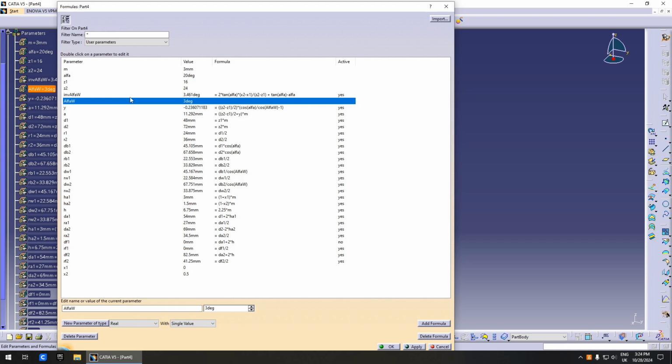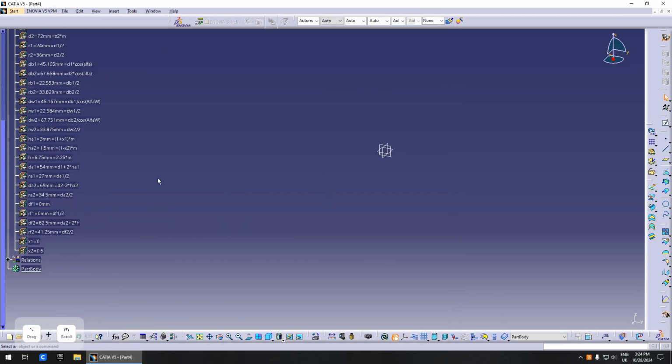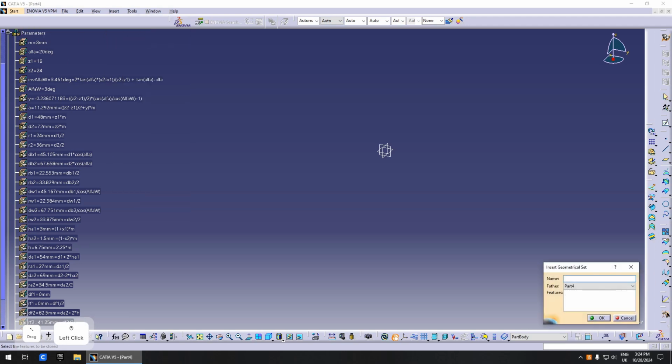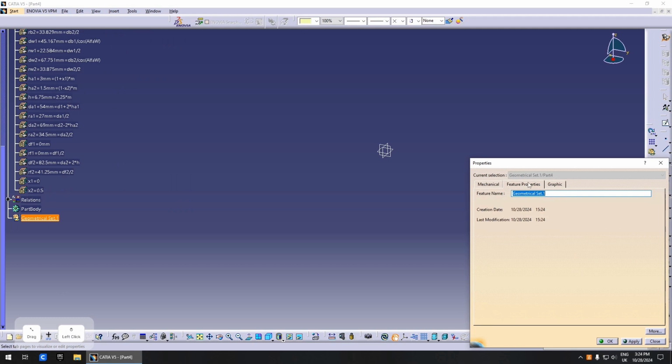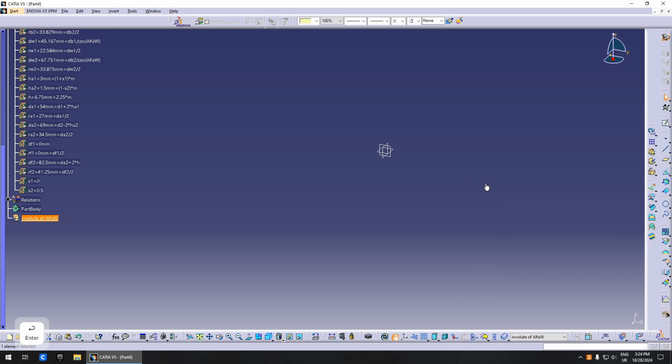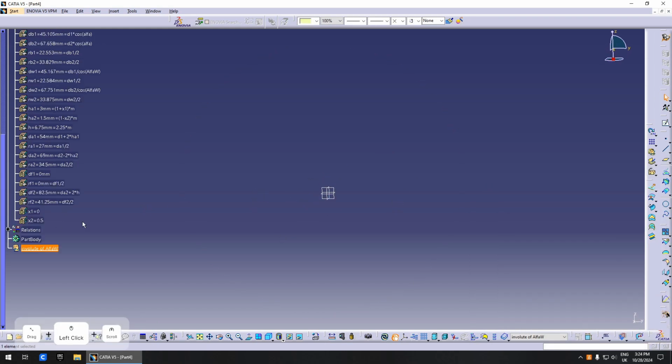And here in CATIA, we can actually have a better solution than that. We can actually trick it. How do we do that? Well, we plot the involute function, and then we match the value to somewhere in that graph. So we have involute of alpha W here, and here we just need to put some points in.